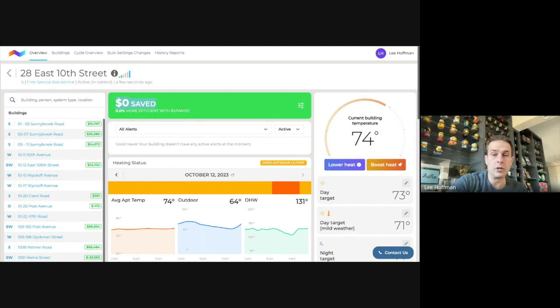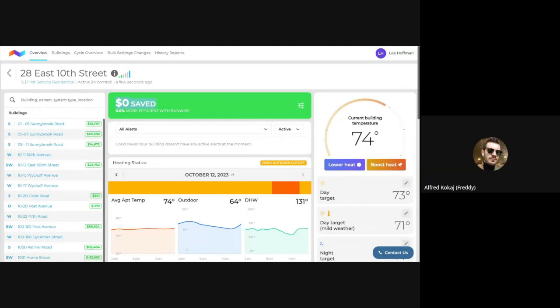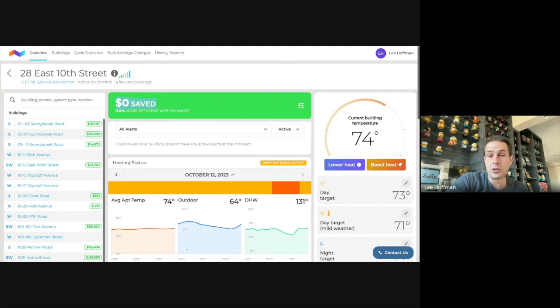We should fire an alert when we detect that, so you shouldn't have to sit there and look for it. We should just literally send you an alert when we think there's a leak. Okay, but 100 gallons for a 100 apartment unit building, it's within that range. Would I still take a look at it? I would probably still take a look at it and see if there's any leaks, just because it's right on the borderline, and maybe you can get it down to 30 gallons, right? And that's 70 gallons saved per day and all the heating required. But with that said, if you do some preliminary leak scanning and you don't see anything, I wouldn't overly stress about it.